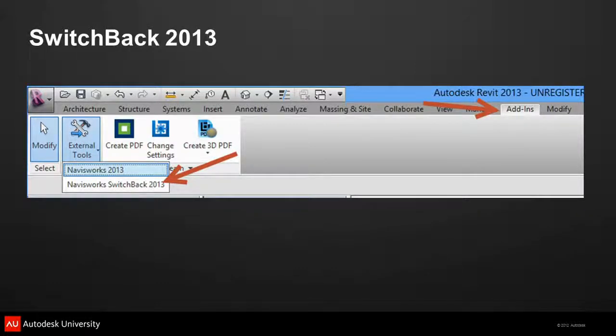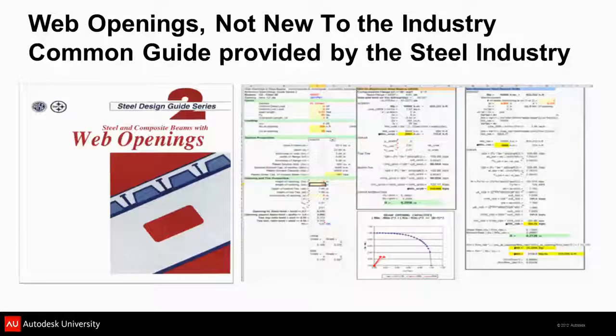I think it would work with Simulate. Yeah, so Simulate does not have clash detection, and so if you were just doing a walkthrough and you found some stuff manually walking through it. But your question was, do you need Navisworks Manage to use SwitchBack? It is a good point. And so we found it to be a very helpful tool with plumbing, especially when we're working out gravity lines. We'll walk down the lines, hit conflicts, and go back.